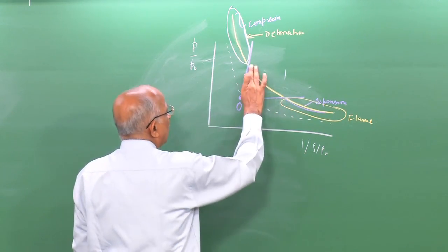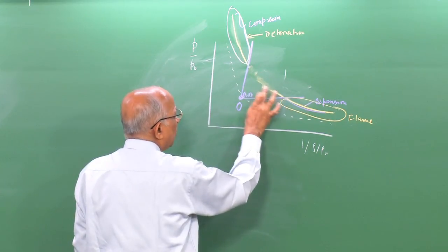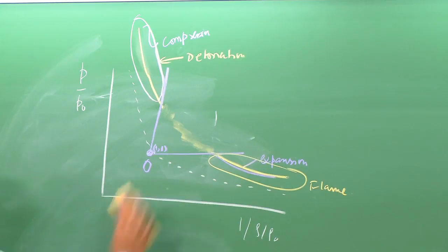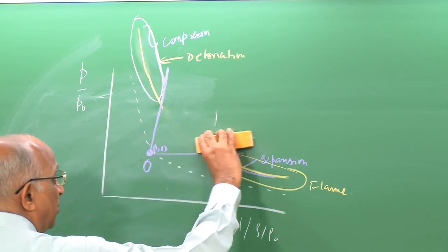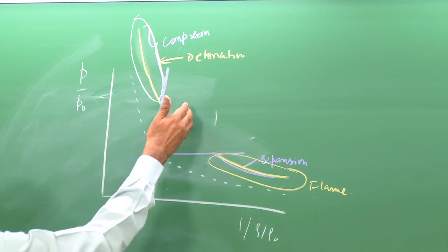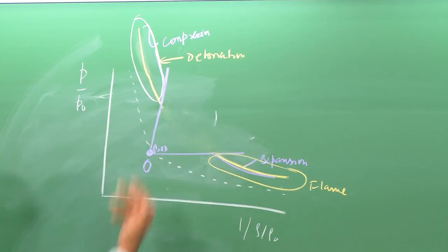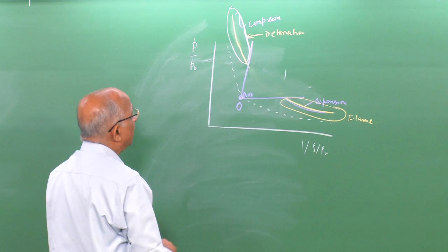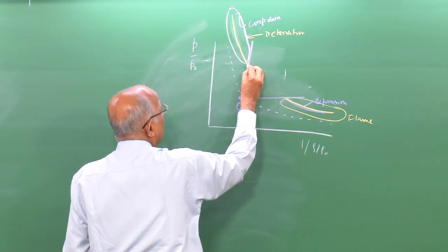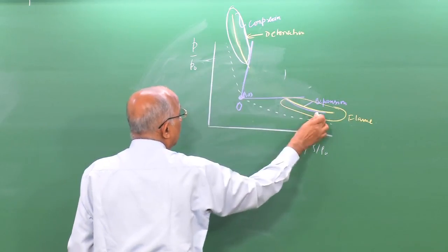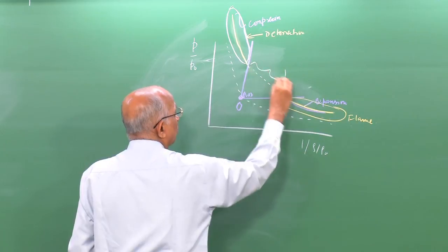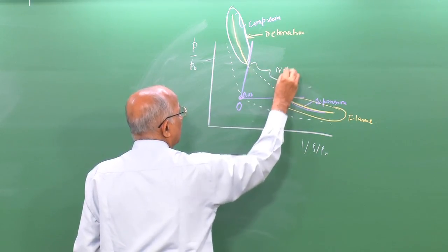Therefore, this zone cannot exist because it gives a contradictory picture in density and in pressure, and if I put it in terms of the Rayleigh equation, I get the velocity to be an imaginary number. Therefore, in practice, this zone is possible, this zone is possible, but the zone between them is not physically possible.